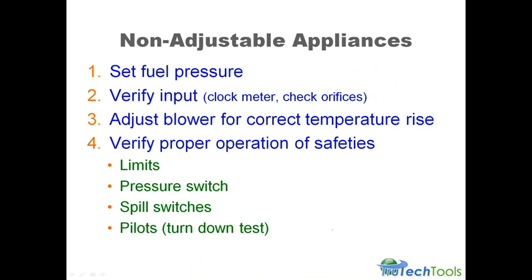So 1/1000 or 3 seconds, excuse me, at 1/1000, 2/1000, 3/1000. If that burner's not lit, you need to shut the gas off immediately, or you're going to have an explosion if it does light. But the pilot safety needs to be adjusted so that it'll shut off, because the pilot's too small to safely light that burner.